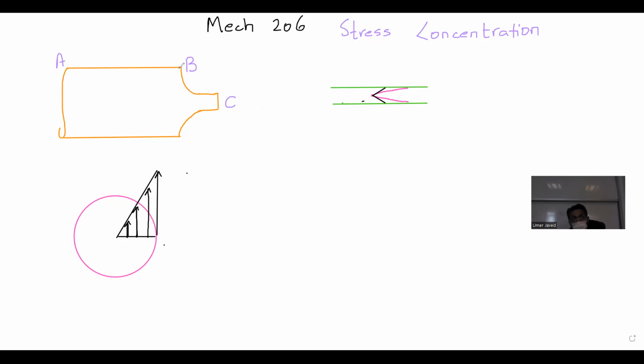Actually, because you have a sudden change in the dia, your stress concentration will give a rather non-linear behavior of these lines. And let me make another line like this. This is going to be a little hard. Please bear with me. And then another line here. So it will be non-linear. Let's call this variation non-linear without knowing the exact shape. So the black line is the life that was beautiful, because now you have stress concentration. And for students who are saying, what does that even mean? I will very quickly make these arrows. The stress lines are trying to squeeze themselves in through this little fellow, right?